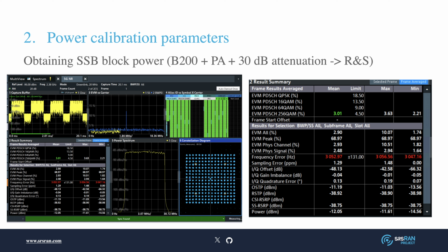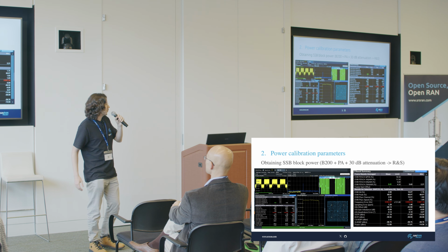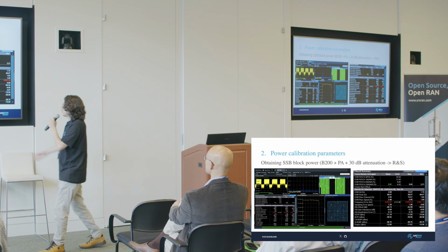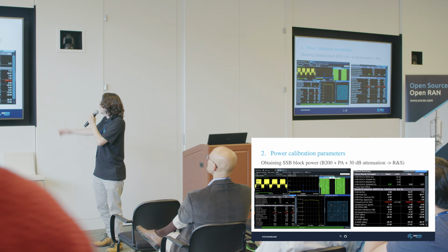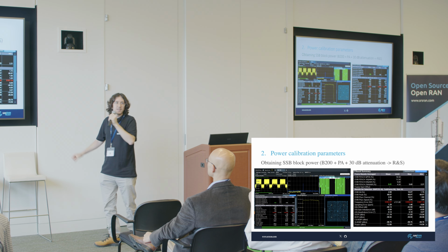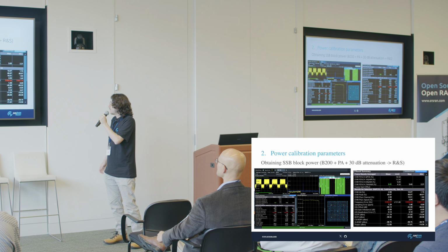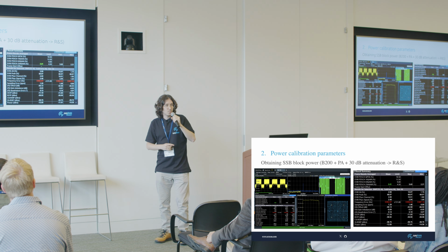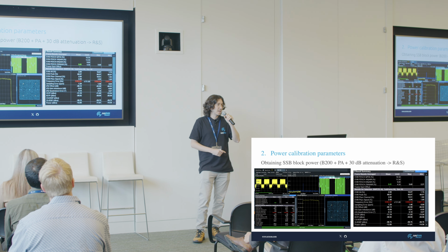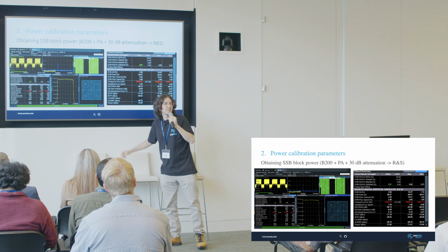Okay, as I promised, this is an example of a commercial grade spectrum analyzer with a 5G application, which of course some of you will recognize. Here you see the parameters of a 5G downlink signal, and on the image on the right, it's zoomed in on the power parameters that you can get. From all of this list, in this particular example, the value that you need to look for and use to configure the SSB block power is the SS-RSRP.